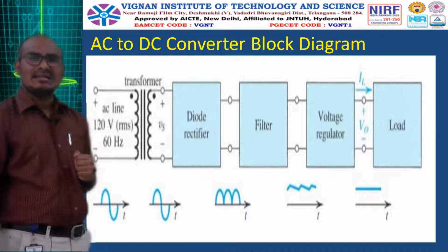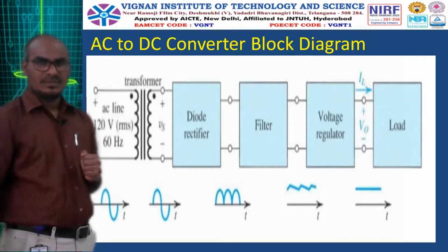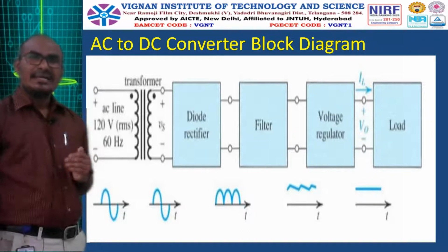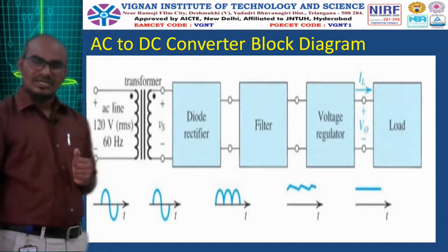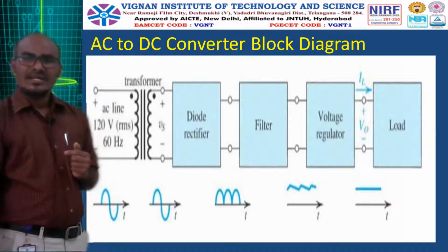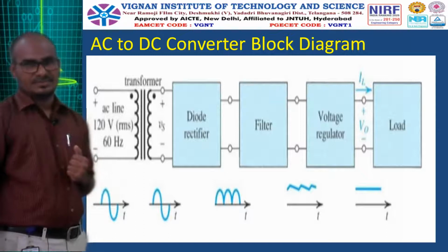This is a single wave that is given. This is one complete wave. Okay, remember this. Now what the transformer will do is, it will convert this 230 volts 50 hertz supply into the diode withstanding voltage, that is nearly 12 volts or 15 volts.